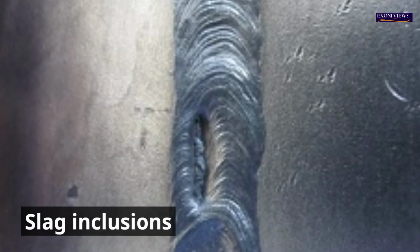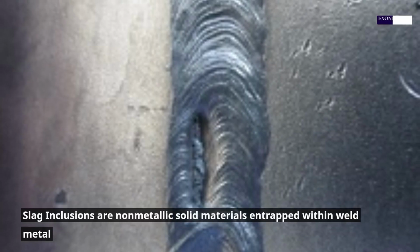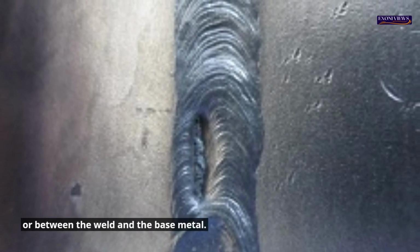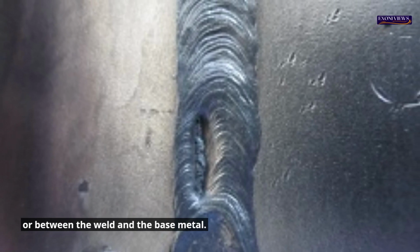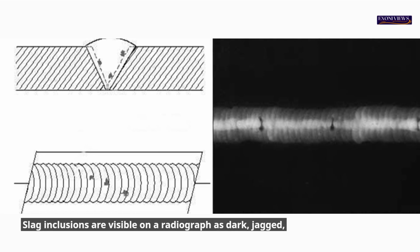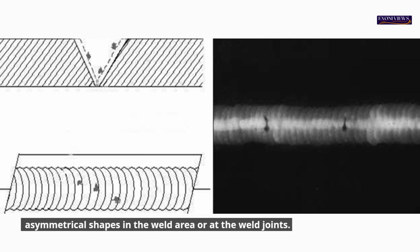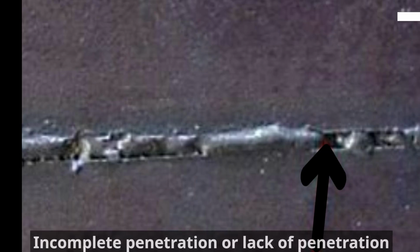Slag inclusions. Slag inclusions are non-metallic solid materials entrapped within weld metal or between the weld and the base metal. Slag inclusions are visible on a radiograph as dark, jagged, asymmetrical shapes in the weld area or at the weld joints.